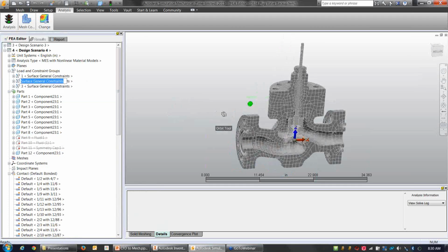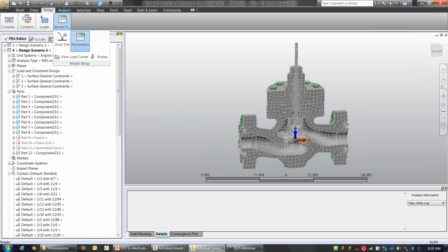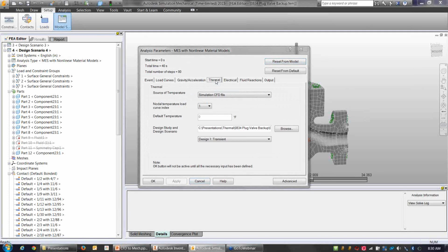Another good tip you're showing there, James, where you can actually paste attributes from other parts and mass select parts to paste those to. I know a lot of customers aren't aware of that functionality, and it can really speed up some workflows. Oh, yes, I love it. It's very handy. So attributes would be element type, element definition, material, and the color.